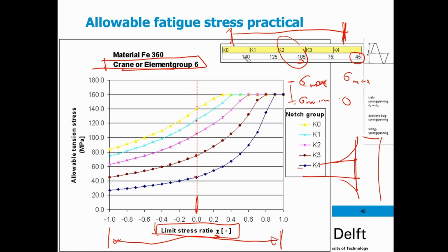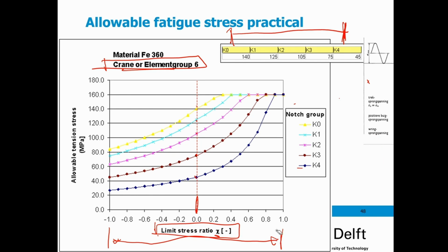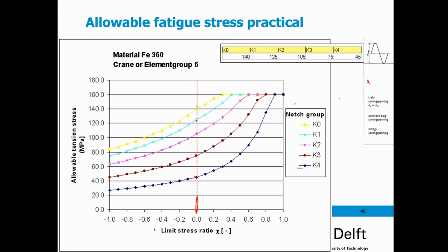And in this method you can clearly see that it pays off to deliver quality work, because the better the notch group, the more attention you pay to avoiding stress concentration factors, the higher the maximum stress you can allow.